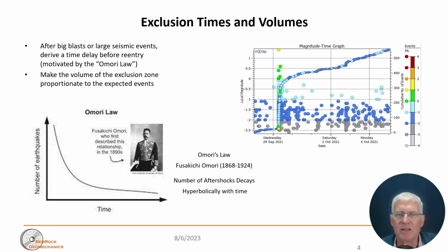And so the strategy here is when you're going to have a big blast that can cause associated seismicity, typically what you'll do is you'll calculate a reasonable amount of time based on your experience with the instrumentation and seismology in the mine. And so you'll exclude people and equipment from the area where big blasts have been while things relax and settle down. And that might take 6 hours, 12 hours, 48 hours, depending on how you tune it up to your particular situation in a particular mining area.